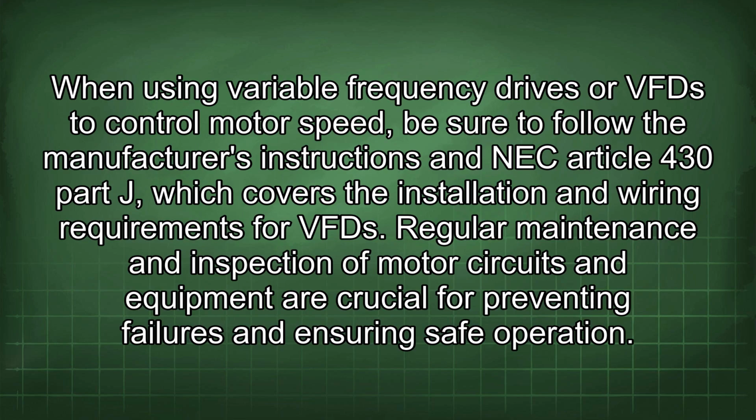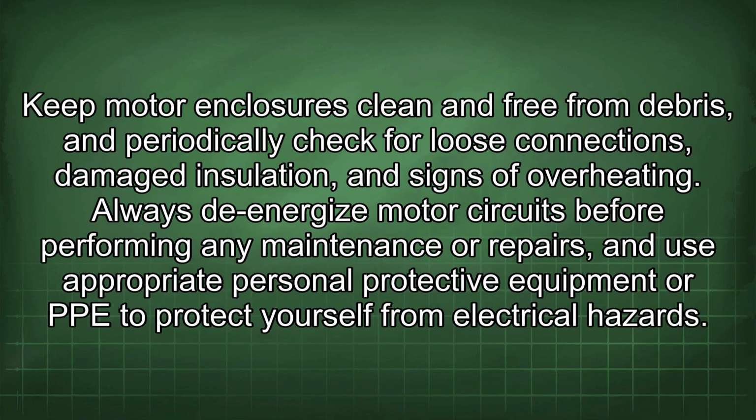When using variable frequency drives or VFD to control motor speed, be sure to follow the manufacturer's instructions and NEC Article 430 Part J, which covers the installation and wiring requirements for VFD. Regular maintenance and inspection of motor circuits and equipment are crucial for preventing failures and ensuring safe operation. Keep motor enclosures clean and free from debris, and periodically check for loose connections, damaged insulation, and signs of overheating.